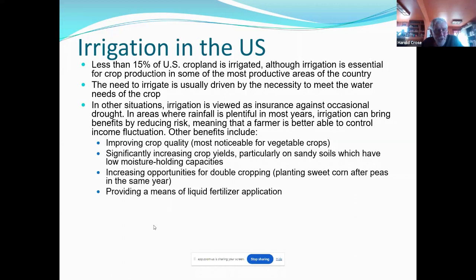In order for nutrient management to work properly in irrigated ag, you need to have an irrigation water management plan, or you're going to leach that nutrient below the root zone. And same thing with our pesticides, or what we call crop protectants. Some of those require dry canopy conditions, and you can't irrigate so soon after, several days in some cases after applying those chemicals. So you have to have a discussion with the grower about their nutrient management plan as well as their pest management plan for the crops they intend to grow. And then you can tailor your irrigation water management plan to those periods very effectively.